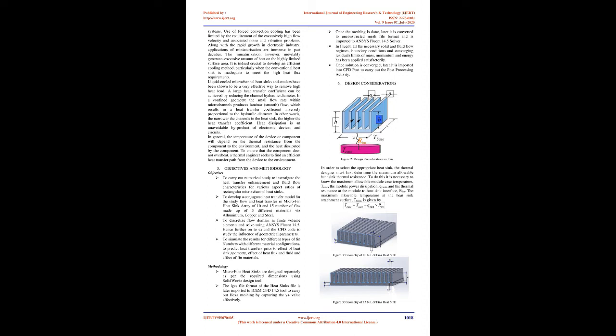Lin et al. [12] had studied the effect of double-layer microchannel heatsink and their thermal performance numerically for a three-dimensional geometry. The working fluid was water and they had examined 6 different types of double-layer heatsinks. They had optimized the dimension of the double-layer heatsink for a particular volumetric flow rate and pumping power and they had reported that the double-layer heatsink should be examined for every particular application as it varies for different working conditions and could not be generalized.